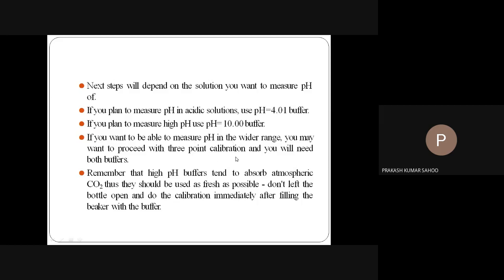Remember that high pH buffers tend to absorb atmospheric CO2, thus they should be used as fresh as possible. Do not leave the bottle open, and do the calibration immediately after filling the beaker with the buffer.